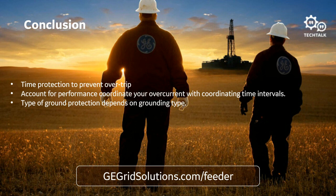The question that's very similar to this, just right above it, is what is the best way to calculate trip times from standard curves? The most difficult way is to take the formula that I just mentioned in the instruction manual and pull out a calculator and do it that way. The way that I've done this in the past is I've implemented that formula into an Excel spreadsheet, and that's a good way to do that, because you can then see the trip time for several different multiples of pickup on a spreadsheet, and that can help with testing.